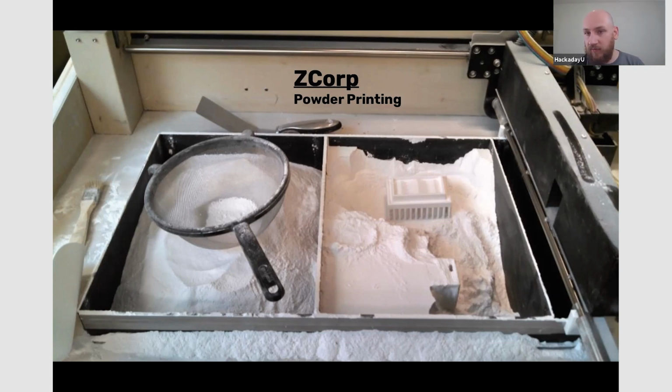And when you do your 3D model, it's going to slice it up by the layer thickness, kind of like we did the contour command. And it's going to be 0.1 millimeter layers or really thin layers. And then that's going to be a layer of powder, a layer of glue, and go to the next layer and to the next layer. And then at the end, you're going to dig out the 3D model, kind of like an archaeologist, basically separating glued powder from non-glued powder. And what you pay for is the amount of powder you remove from the machine, as well as the amount of glue. So it's sort of a combo price.